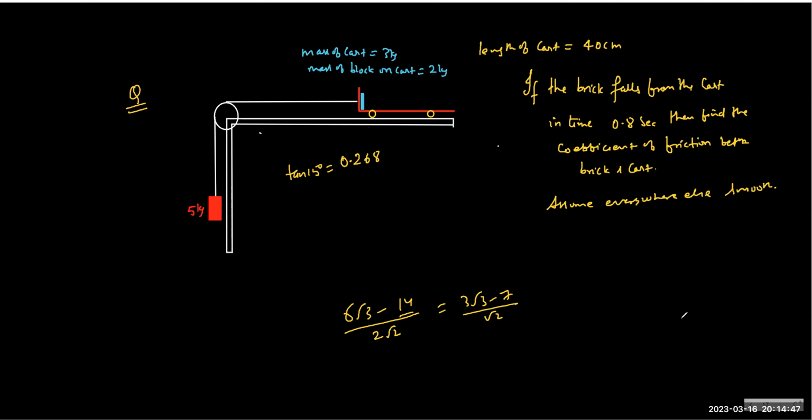So that question is similar to the two block problem which we have solved, right? The N12 we used to have earlier is now replaced by what? The spring force. So the role of internal force is replaced from the reaction to the spring force. There is no difference. So what you are supposed to do now is directly use the formula which I derived and equate with Kx, and I'm done.